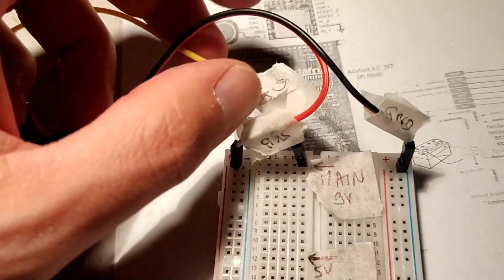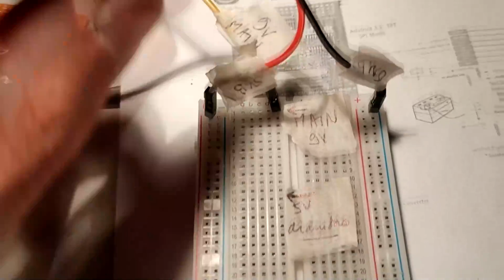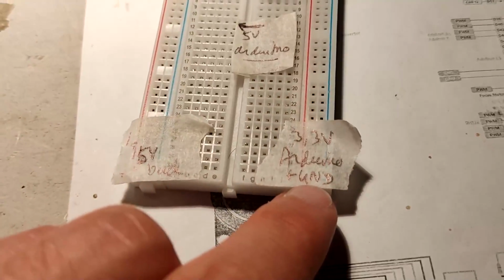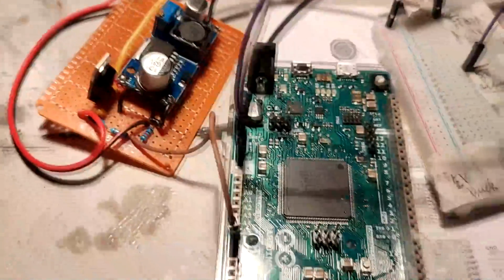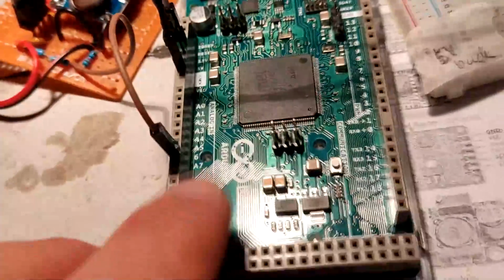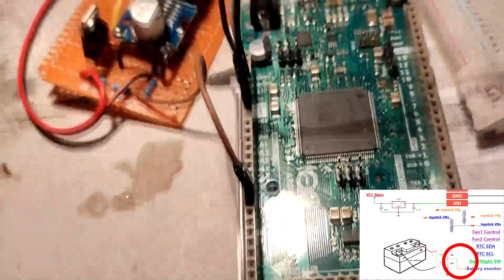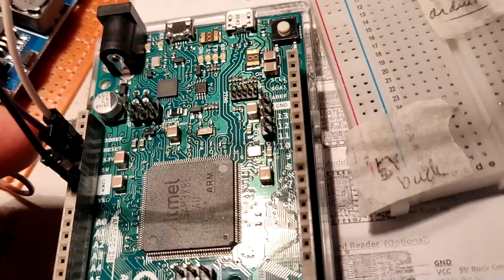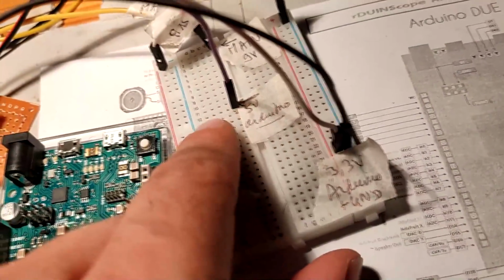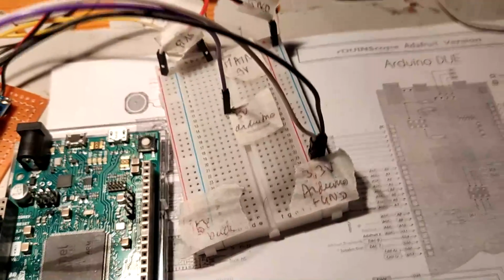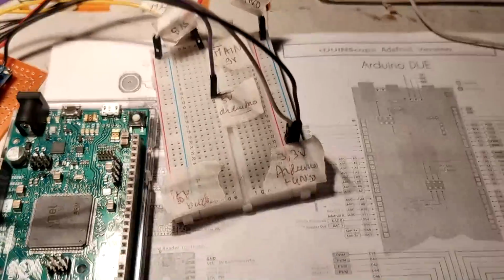I have the 9 volts main coming from the voltage regulator. I have the ground, I have the 3.3 volts emplacement reserved, and also for the 5 volt buck on Arduino. Here this is the cable for the monitoring on the A7 pin. I plugged here 3 wires for the ground, the 5 volts and the 3.3 volts. They go to the breadboard at the emplacement, one for the 5 volts Arduino, for the 3.3 and the ground. And I will plug the modules on this breadboard on this emplacement to power supply it.